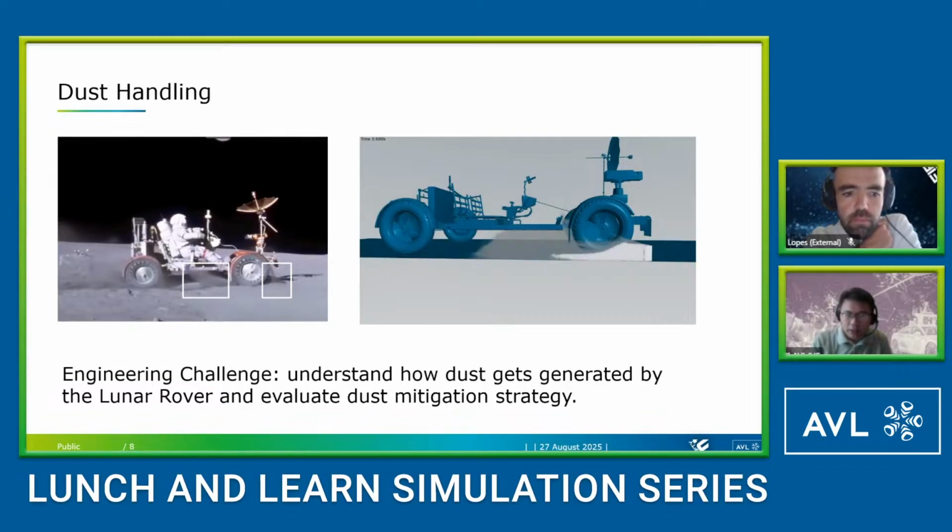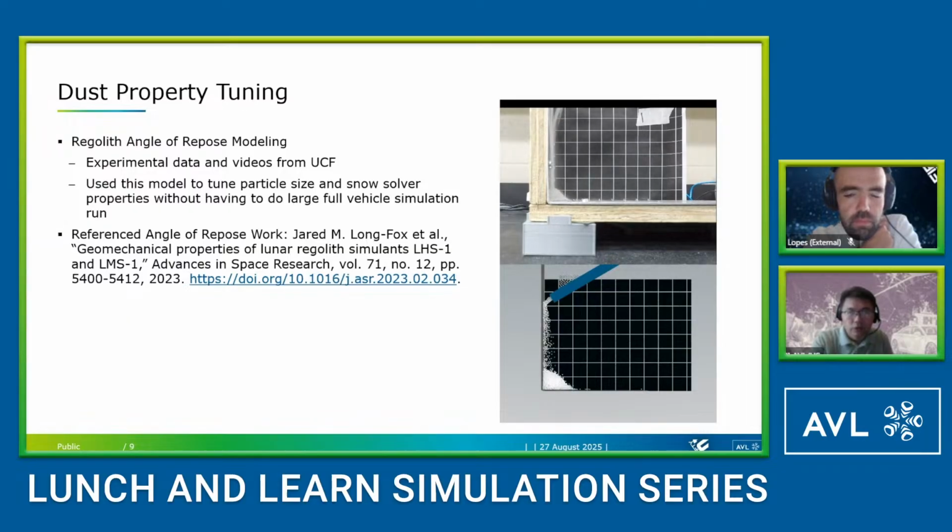And then last but not least, we can simulate dust, as I'm going to show you in the next slides here. So the dust properties need to be calibrated so that we can model the dust in a more realistic way. Here we use this angle of repose data from experimental work at UCF.